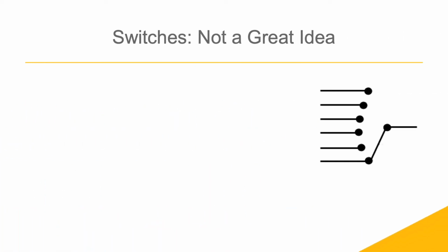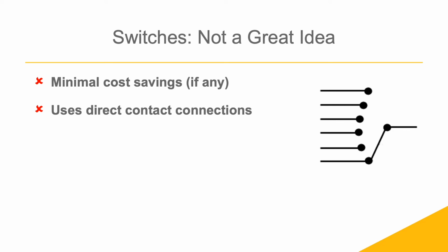It is natural to consider mating a single channel power meter with an automated optical switch as an alternative to a multi-channel power meter. However, the compromises of this approach rarely outweigh any slim cost savings it might produce. Precision switches are not cheap, but that is just the start. The detectors in the OPMs do not require direct contact with the fiber, whereas connections to the switches do, which creates an opportunity for damage.